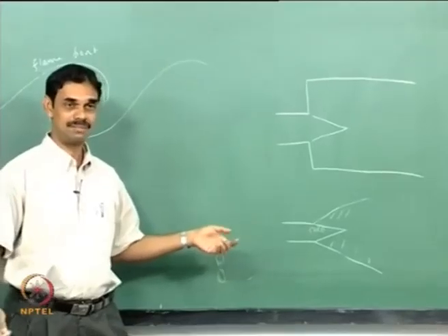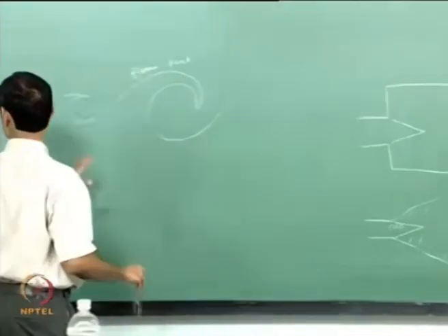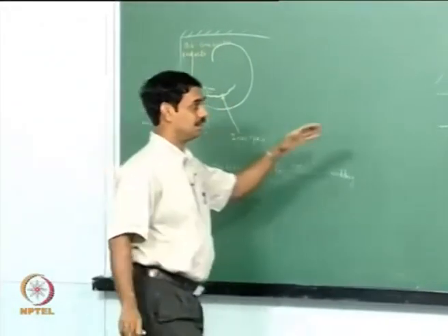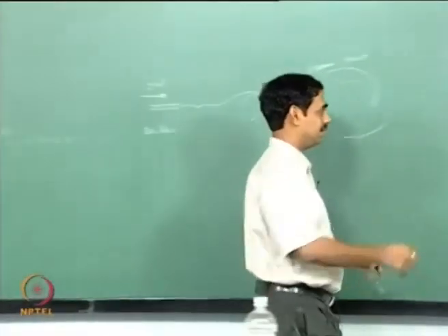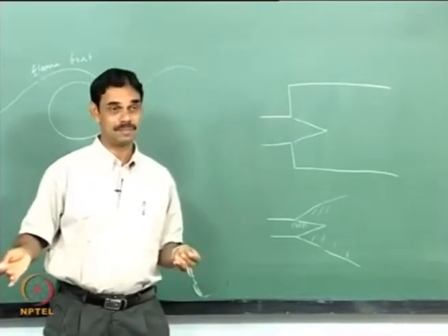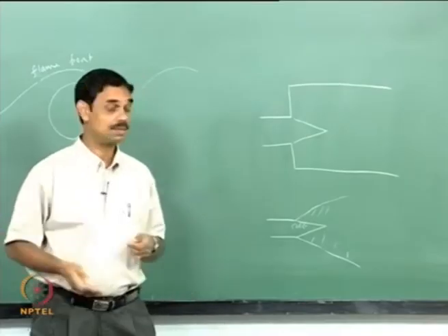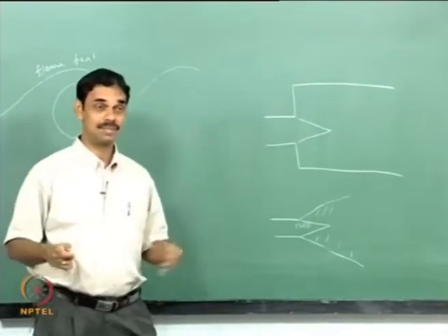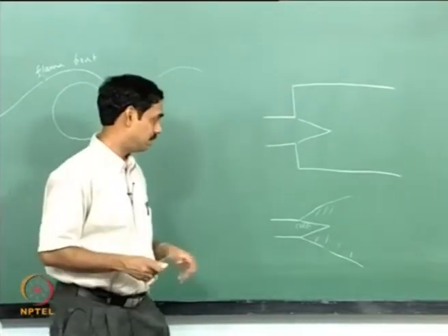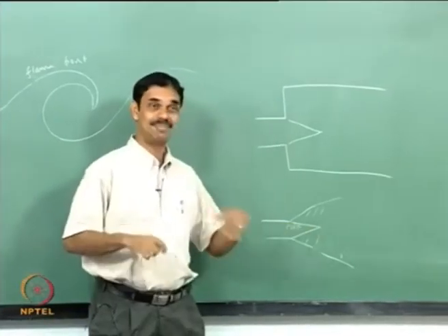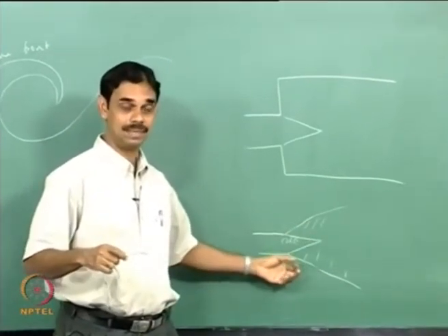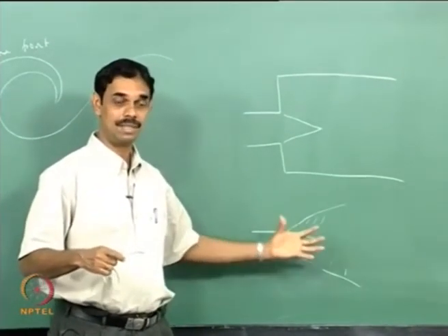but in reality it's very far from this. This is more like the reality, and this is how the flame happens, and it's never ever that you will have a nice flame standing like a V. I mean yes, it is possible in a simple Bunsen burner flame or something like that, but not in a real combustor. You would have vortex shedding if it is coming at any serious velocity, and you would have a vortex roll up and the combustion would be periodic. And if you have a jet, the jet will have vortices, and if you time average over a large time you would get this picture, but the instantaneous picture is highly unsteady.